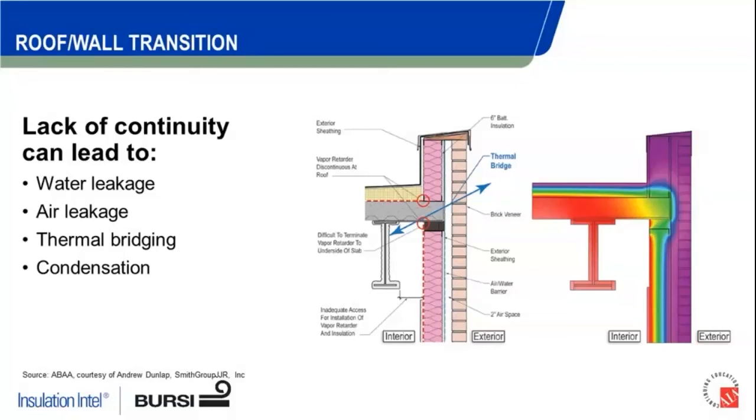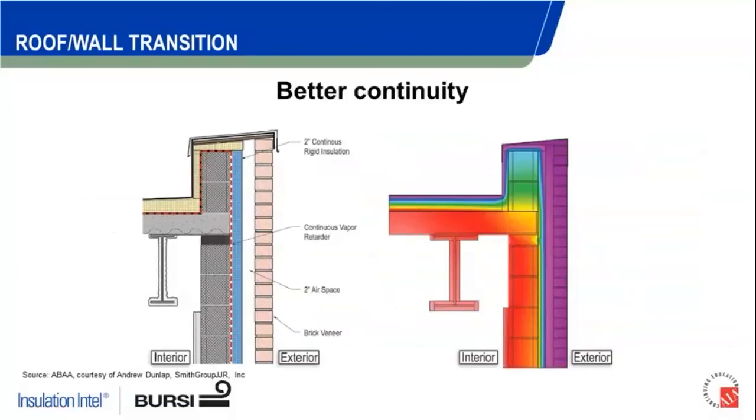We're just showing a wall system here that's not thermally broken. You've got a slab edge condition that's exposed right there. And you can see by that thermal image on the right that the end of that slab edge is green, right? That essentially says that slab edge is cooler than the rest of the slab edge that's red. That means we're having conduction thermal bridging occurring at that stage in our wall system. So maybe a little bit better option here.